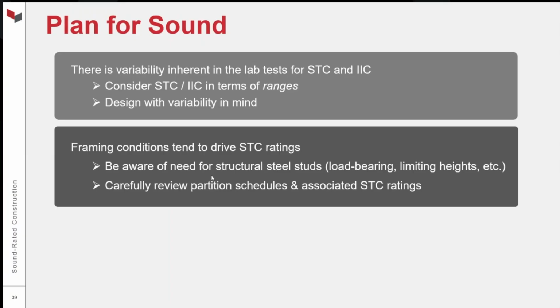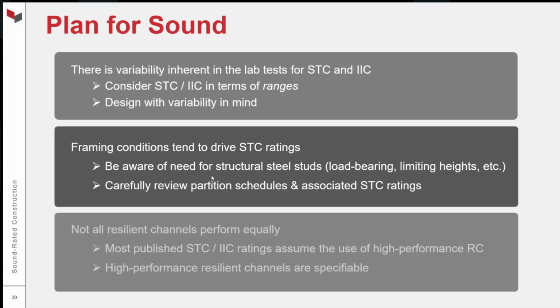Carefully review your partition schedules. If you're a designer, really scrutinize and be thoughtful when you're putting together your partition schedules. If you're a contractor and you're inheriting a partition schedule with STC ratings, look closely at those ratings and make sure the STC ratings are applicable to what you're seeing on the drawings.